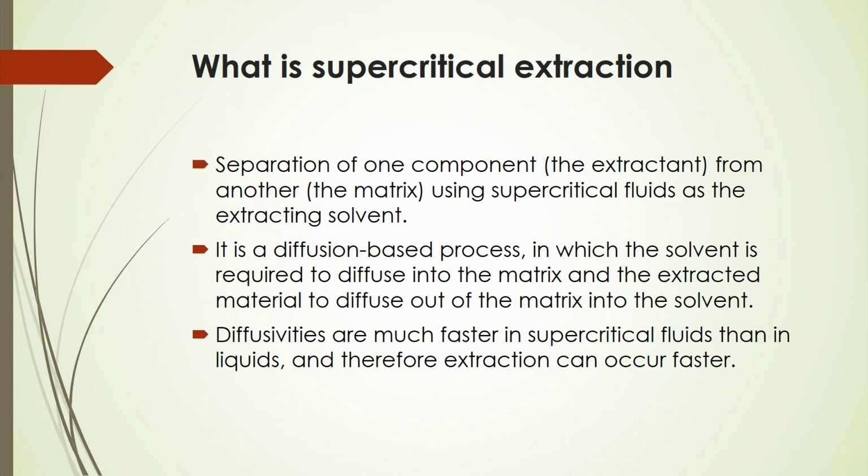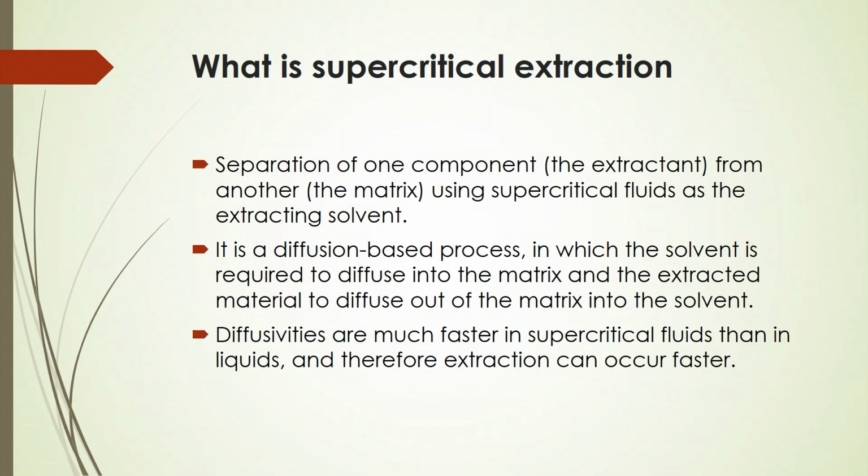Now, what is supercritical extraction? As per definition, it is the separation of one component, the extractant, from another, the matrix, using supercritical fluids as the extracting solvent. It is a diffusion based process, in which the solvent is required to diffuse into the matrix and the extracted material to diffuse out of the matrix into the solvent.